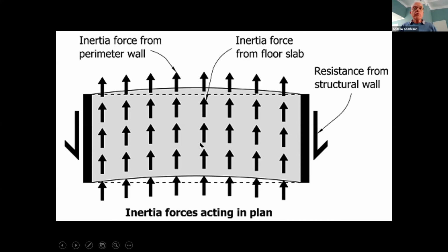And so in the building that you are designing, the role of your floor slabs is to transfer the forces into your moment frames or shear walls. Your floor slabs also have to tie your building together so that during an earthquake, it doesn't fall apart. And so your floor diaphragms are really important.